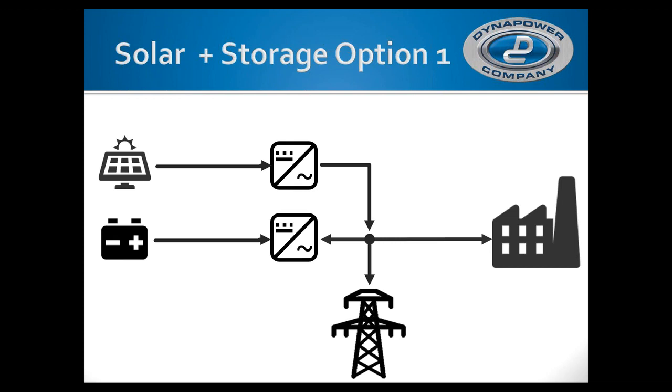The considerations here, again, at the end of the day, if what we're trying to accomplish is a resilient system, and I do apologize because it's not in the slide here, at some point you've got to have a break from the grid, right? If we're creating an island, we've got to open up the connection to the main grid to support that load and continue operation. What you're not seeing in this diagram, because it's a bit oversimplified, is that part of creating a resilient system is going in with the controls and the protection equipment to open up the connection to the grid.